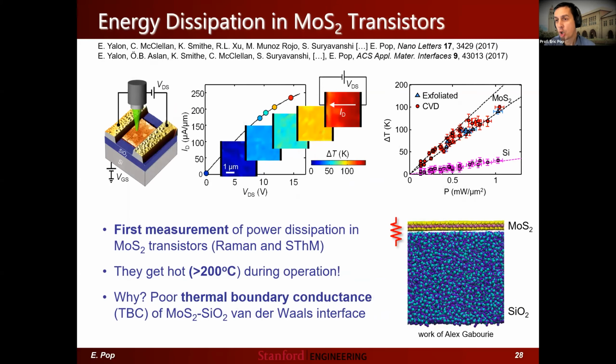So, I mentioned earlier that our transistors are thermally limited very often. We've investigated that as well on larger transistors. It's very hard to do this on nanoscale transistors, but if you make larger transistors, you can measure this with Raman thermometry, just like a very nice talk that we saw earlier. And essentially here we measured the thermal properties of an MoS2 transistor during operation. Here we plot the temperature at every point on the IV curve for this particular transistor.